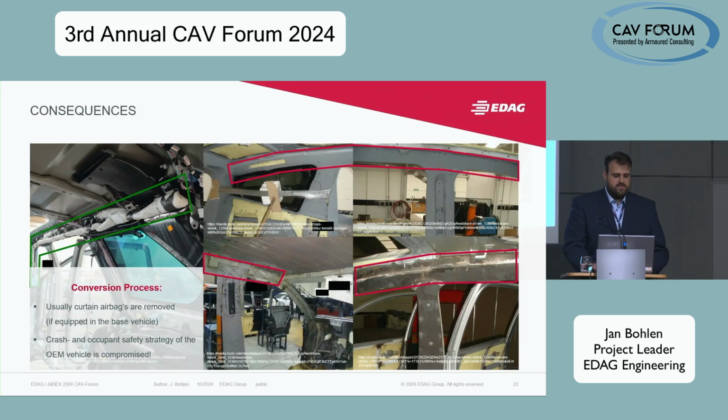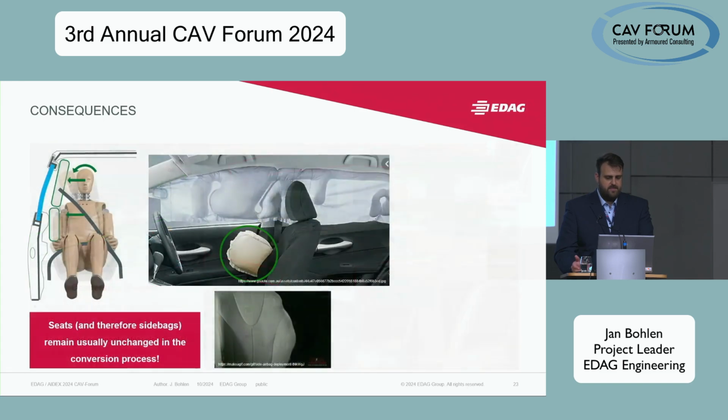The reason is fairly simple. During the conversion process, to make space for the armor, most manufacturers just spare the curtain airbag. They remove it, and of course, therefore, the crash and occupant safety strategy of the OEM vehicle is compromised. The vehicle will act totally different, and that means a huge danger for the occupant in the end.